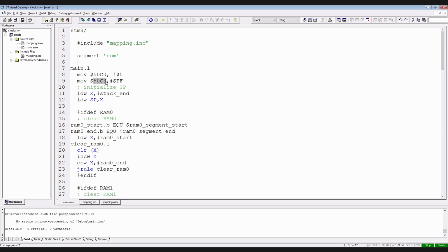However, in low power MCUs, developers fight even for a single microwatt. Mostly those kinds of MCUs are designed to work with batteries over a long time period without maintenance. Hence, there is a need to enable this register because it's disabled by default in order to reduce the MCU total power consumption.